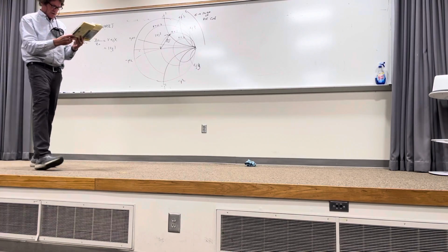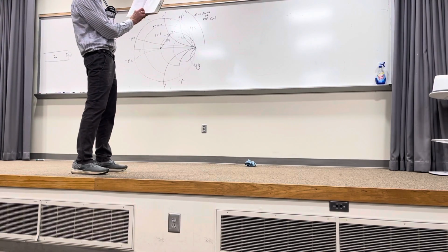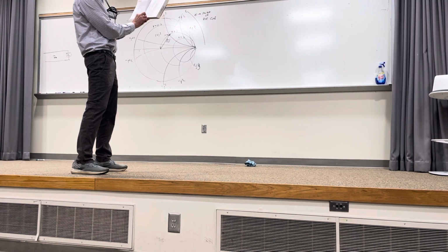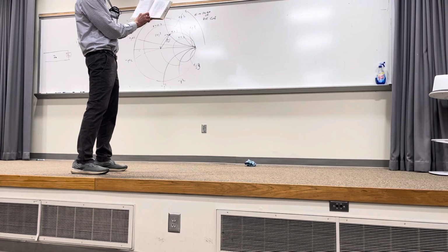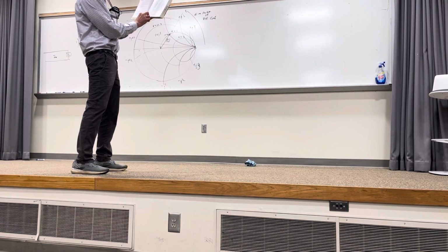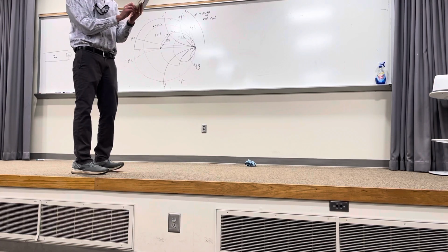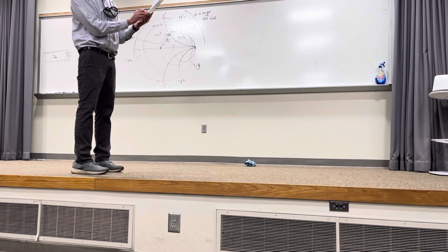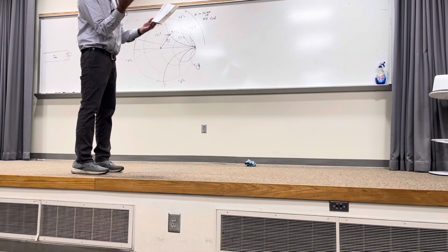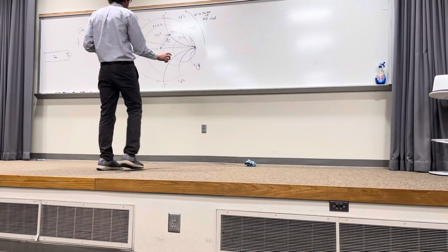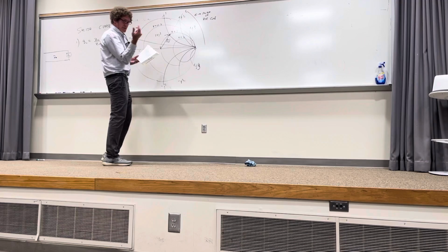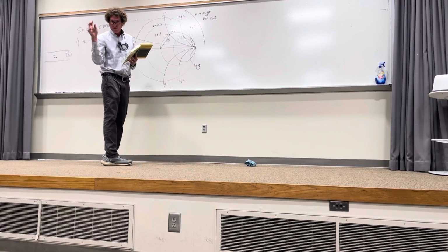Go at the very bottom here in the Smith chart, you're going to see something where it says reflection coefficient E or I. Do you see that, the very bottom one? E represents voltage. It's the old English way of representing voltage, or current reflection coefficient. And if you take the length of this, this is why you need a compass, or you actually need some way of gauging the length of this.